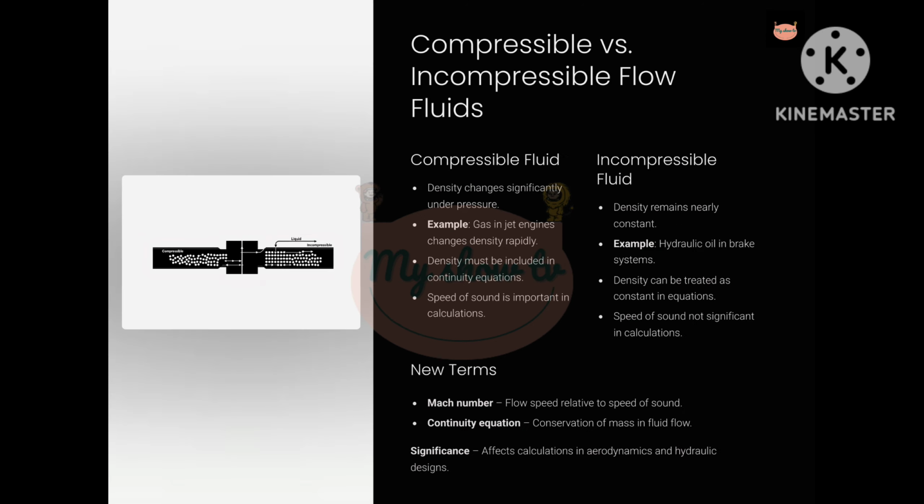Slide 4. Compressible vs incompressible flow fluids. In compressible fluids, density changes significantly under pressure, common in gas pipelines or jet engines. Incompressible fluids, such as hydraulic oil, maintain constant density, simplifying analysis.